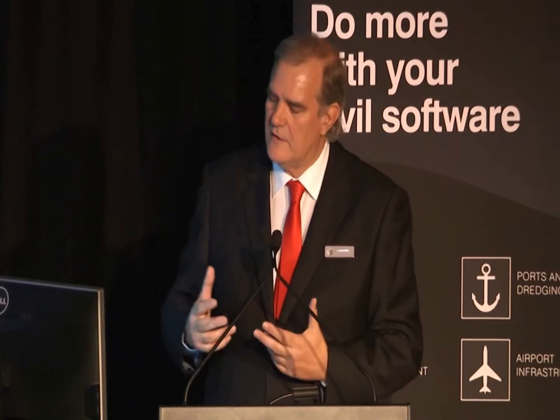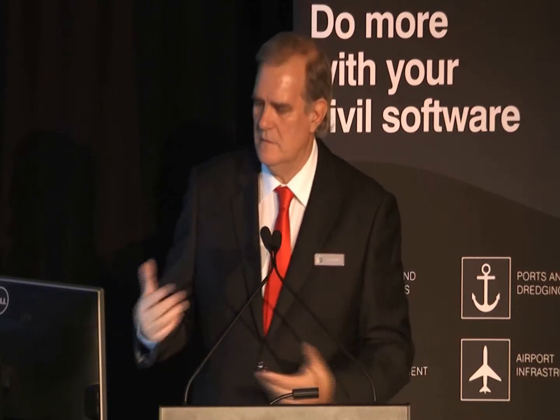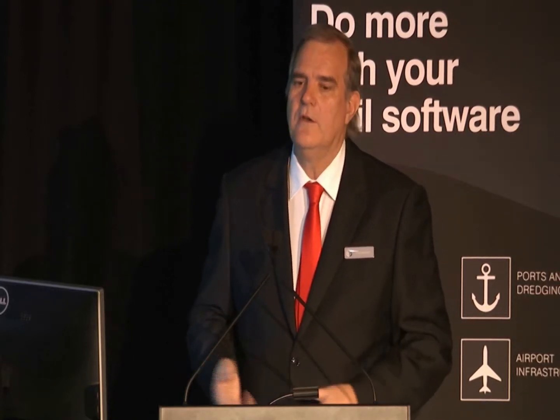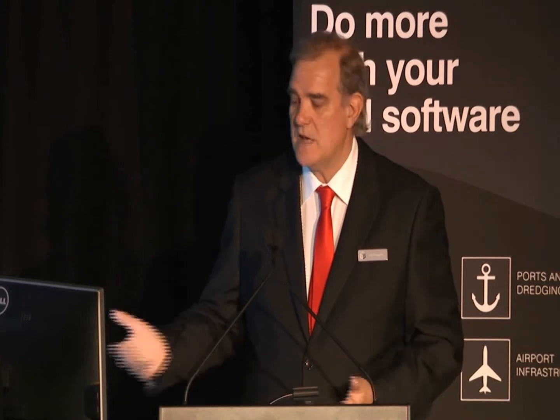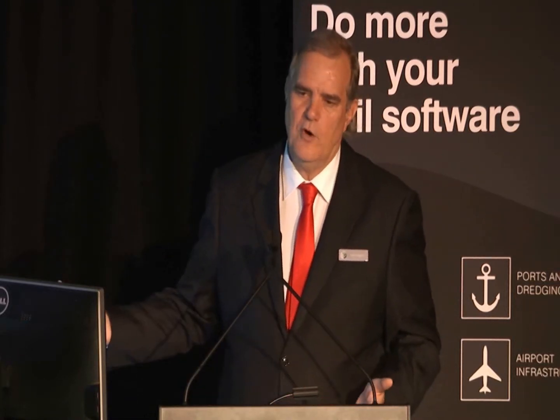ADAC is a Queensland as-designed, as-constructed format, which is starting to be allowed for handing in your data to a lot of the authorities electronically, so they can use it to go into their systems rather than working from drawings. Then there's ePlan and eSurvey. eSurvey is in New Zealand, where all their cadastral work is done online. You don't do anything any other way now. That is going to be introduced in Australia over the next 12 to 24 months. So it'll be a huge change for the surveyors, but we believe, again, it's an open standard that everyone can work with. ADAC, I think, over the next 12 months, we'll talk about in a couple of days' time. It will also start to come in over the next 12 months.